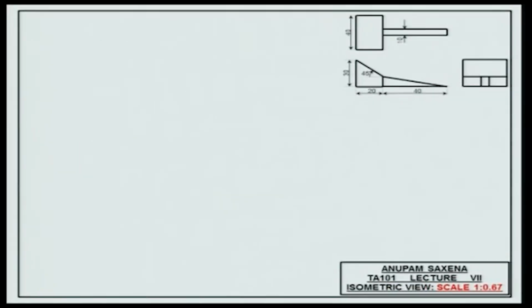First thing, get one of the axes, the x-axis. Now realize how I am drawing the axis. I am drawing the axis opening towards you, not opening away from you. X-axis, y-axis and the z-axis. First thing, both x and y 30 degrees from the horizontal, z-axis vertical.